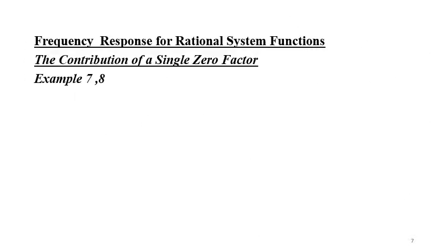So to summarize, we have considered two examples, one for the zero and one for the pole, although in the pole case we had a pair of poles. If you compare the two examples, you can see that the contribution for the zeros are opposite to what they are for the poles.